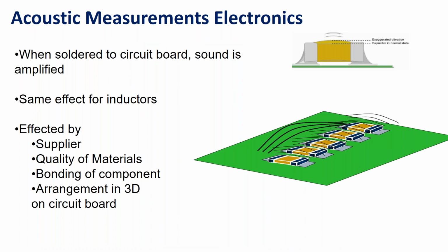If you have an arrangement of these capacitors on a circuit board like we just showed, even though an individual one might not cause enough vibration to become audible, a series of these together on a circuit board can become audible. The circuit board at certain frequencies or modes can amplify that sound and become more of a problem once you have these arranged on a circuit board.